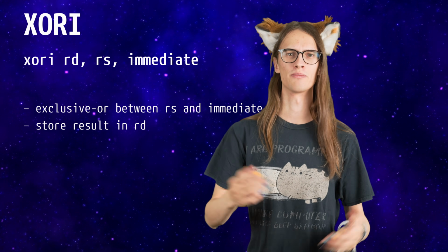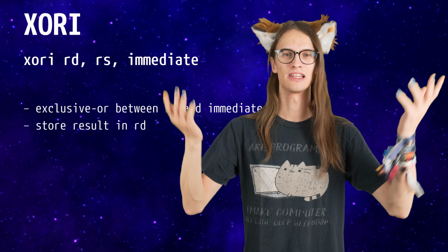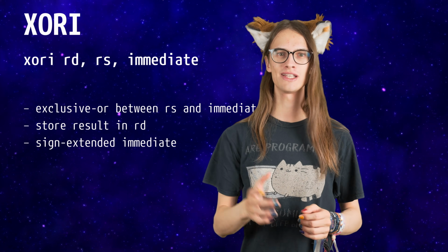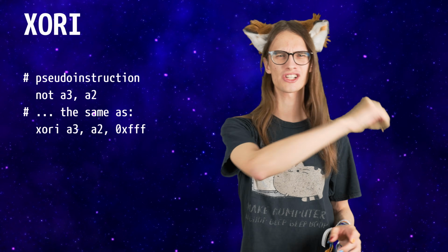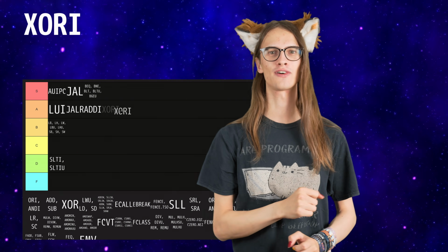If you already know the instruction list, hold up. There is a reason why I am splitting XORI from the other 2. Again, on the surface, this is just the instruction for bitwise exclusive OR, XOR, between an immediate and a register, really nothing special. However, since the 12-bit immediate is sign extended, this means that we can easily XOR a register with all ones by just using the immediate hexadecimal FFF. And if you know anything about XOR, you know that this will flip all of the bits of the operand. A logical NOT. Absolutely no need to use a separate instruction here. A tier for XORI.